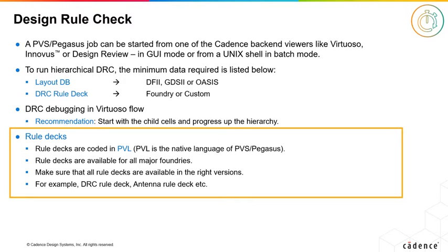Regarding PVS rule decks, generally, they are coded in PVL language. PVL stands for Physical Verification Language. PVS rule decks are available for all major foundries in the market. For accurate PVS runs, users need to ensure that the rule decks are available in the right versions.